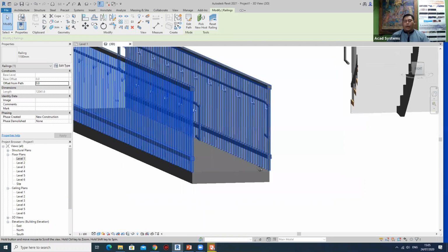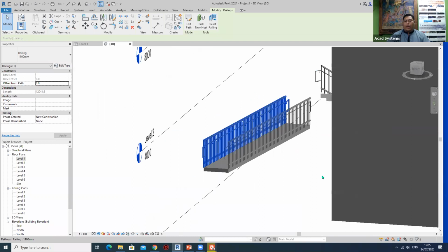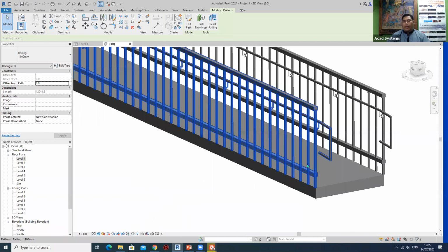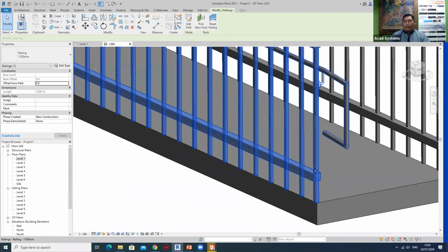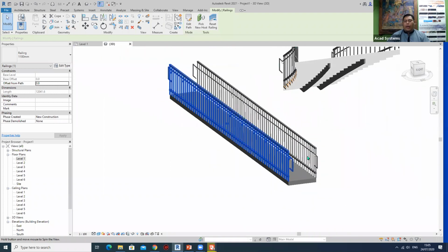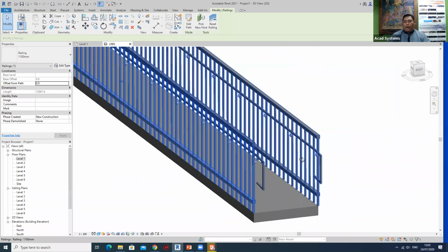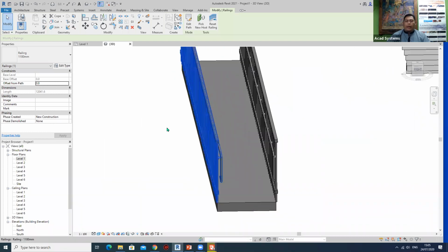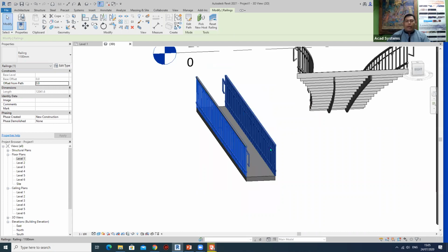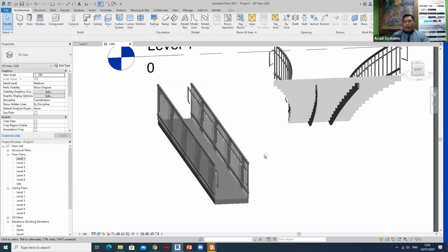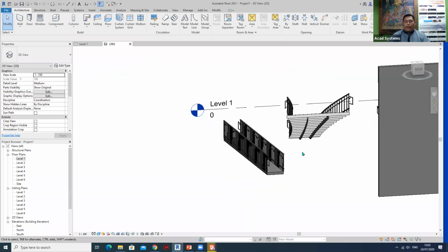So it applies regardless of whatever railing type you wish. The 200 mm gap that I created is set here, and I have also added the kick rail as my additional railing. I also added the guardrail for you to define the guardrail position. It can be inside or outside the railing, depending on the situation, left or right. So that is actually the fundamentals of modeling staircase and railing.